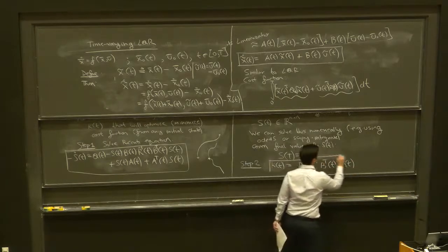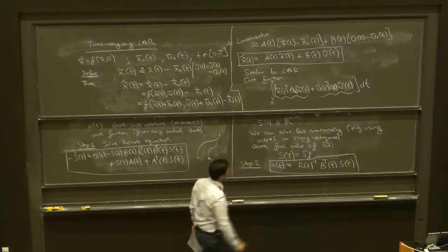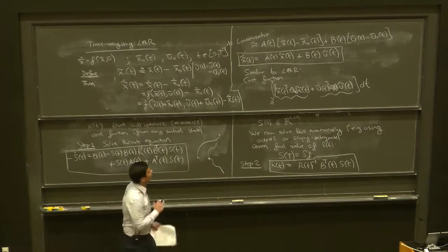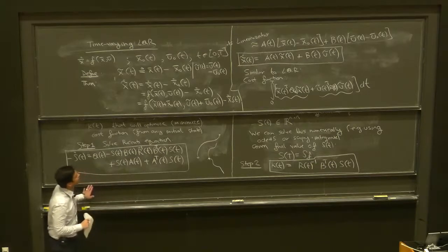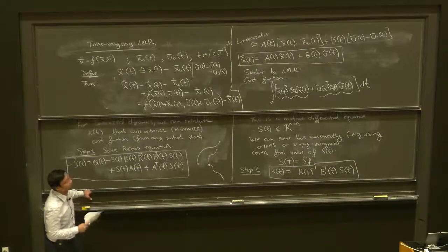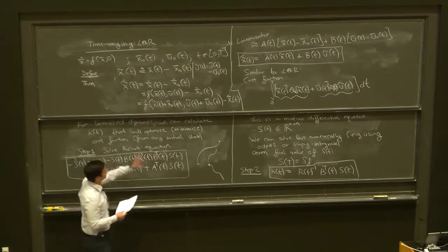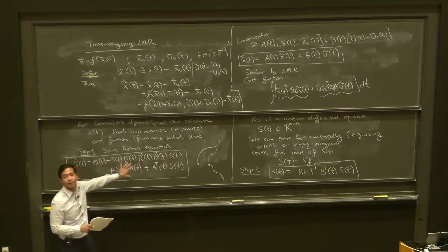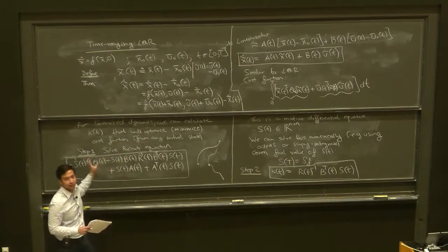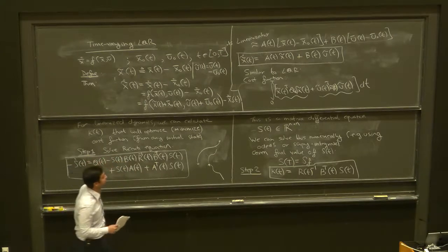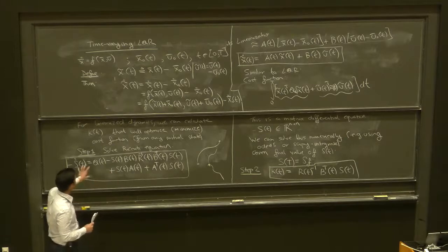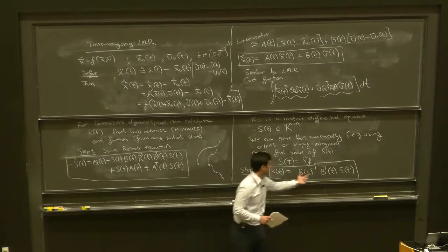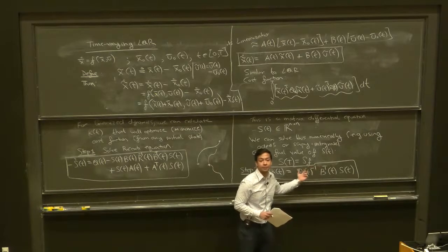And that's the optimal gain matrix. All right, so again, let me just pause for a second and make sure the process is clear and what I'm claiming is clear. So the process is this two-step thing. You solve this differential equation, which looks a little bit ugly, but you're not solving it analytically. You just call ODE45 or some other numerical integration technique. You get S at every time by solving this differential equation, and then the gain matrix is just this. You just multiply these matrices.